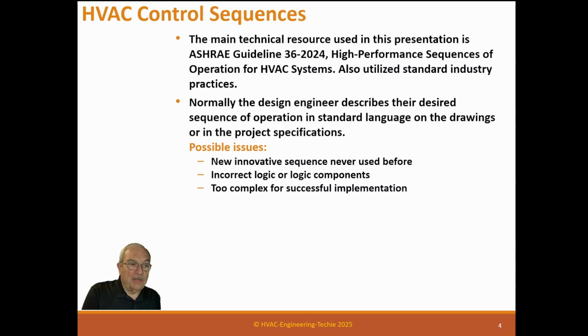I mean, you can, but it takes forever and ever. And then in the end, because it's so complex, it's just full of errors or things that are going to mess up in the field. So we try to use a stupid principle. That's keep it simple. The more complex a sequence is, the more difficulty it's going to have remaining and providing persistence in the system. And the reason is because not only do we as commissioners or we as programmers have difficulty putting it in and making it work and testing it, but operators will have a terrible time trying to keep it running correctly.